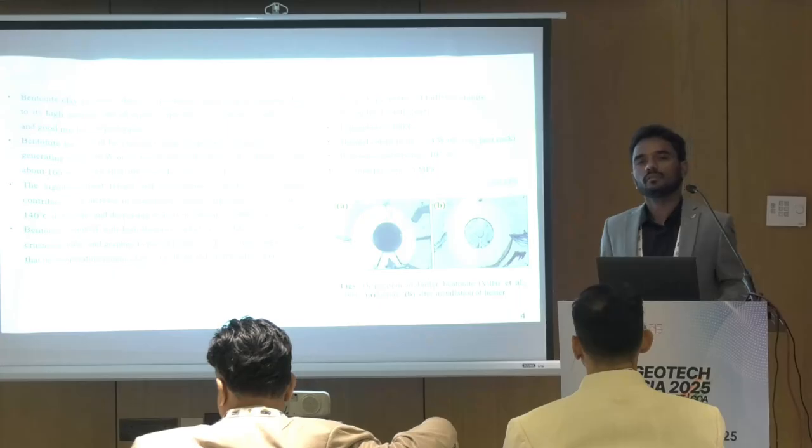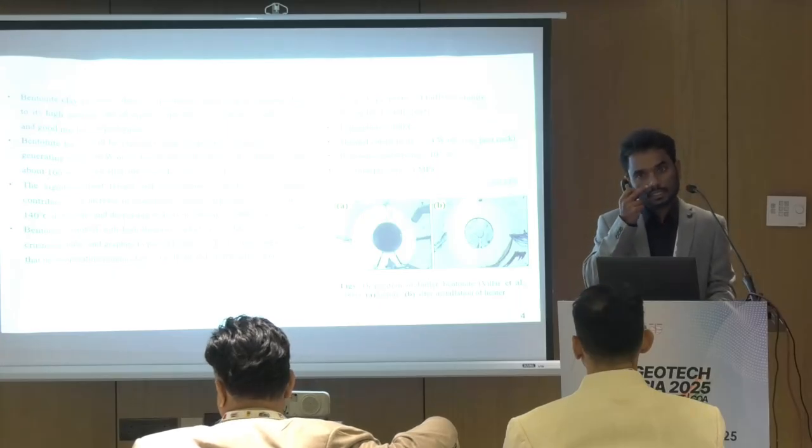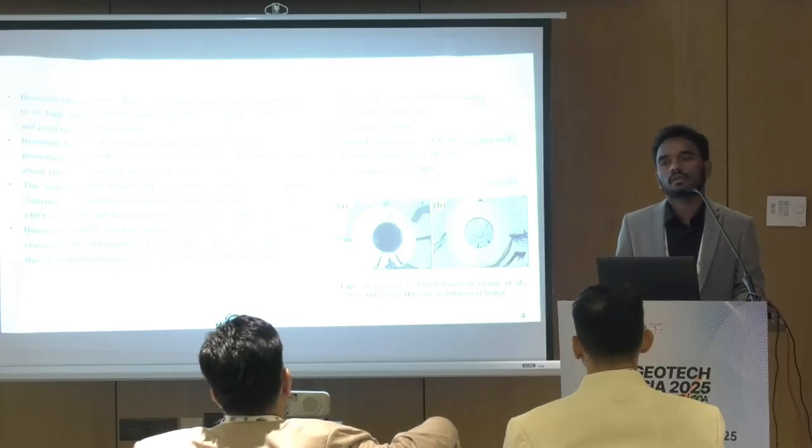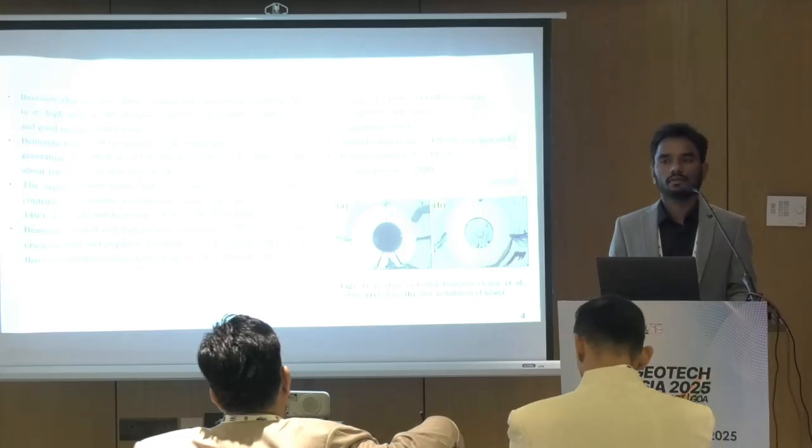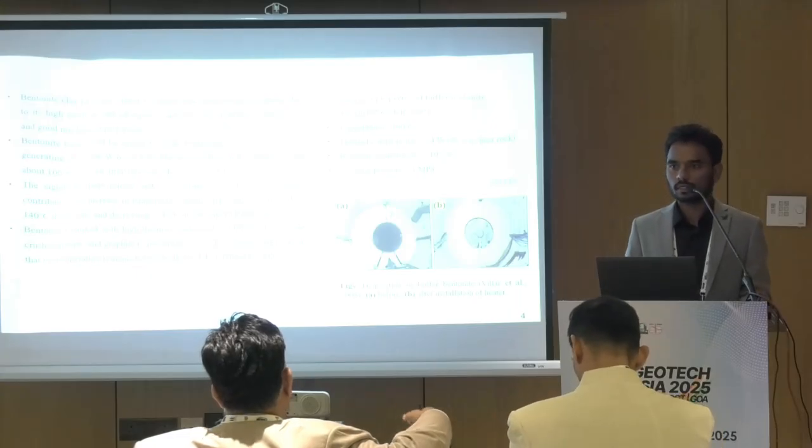But one of the major drawbacks of bentonite is that it has low thermal conductivity. If the thermal conductivity is low, the heat flow is not uniform and its rate of heat flow is very low. So it is mixed with sand and graphite, or other higher thermal conductivity materials.